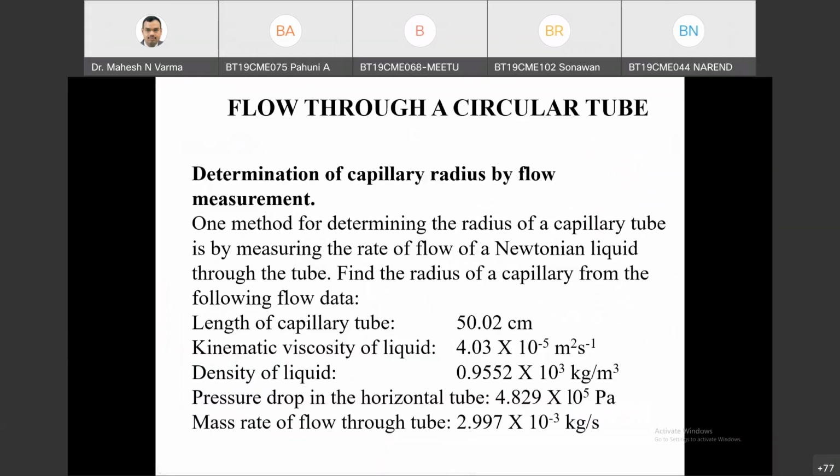Yeah, but why do you need to use the Chilton-Colburn analogy here? From here I'll get the friction factor, and then I know the power that the pump should apply should be able to overcome the work done by the drag force. Okay, all the data is given, no? Viscosity is given.